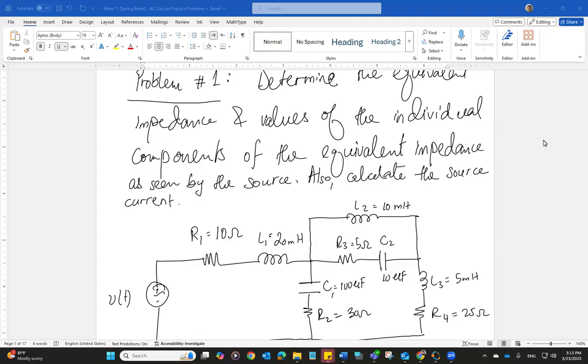It's going to be resistors and reactance corresponding to inductors and capacitors. So combination of impedance in series, combination of impedance in parallel, and KVL, KCL, Thevenin voltage, superposition, all those things that we learned for DC circuit analysis are still valid for AC circuit analysis. So basic rules do not change.